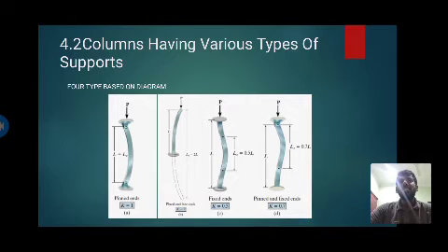The effective length was developed for the case of a column having ends that are pinned or free to rotate. In other words, L in the equation represents the unsupported distance between the points of zero moment. This formula can be used to determine the critical load on the columns.